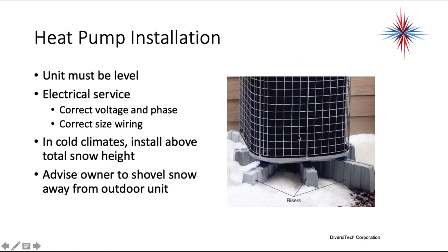Or you pull the cover off and you bolt through the bottom of the pad and through the bottom of the unit into concrete. If it's a rooftop unit, again in northern climates, it has to be installed in a way where it's above the snow level. In the southern climates where there is no snow, you do need to make sure these units are tied down to the roof in some way or another. Make sure you check with local building officials and local building code.